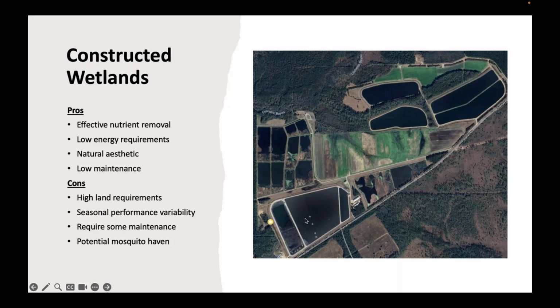This big pond here is our primary treatment pond, and all these little ponds are areas of constructed wetland. The idea here is you're running your effluent through, the nutrients are being soaked up by the growing plants within the wetlands, and by the time you reach your actual discharge point, you've let Mother Nature do all the work for you from a nutrient removal standpoint. So it can be effective. I've seen it be effective at different sites.